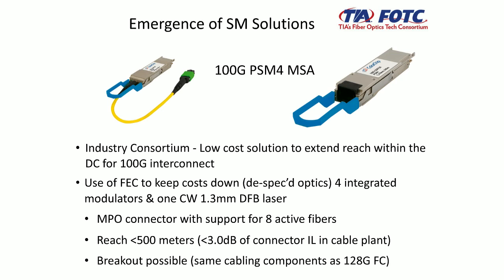This device actually has a single laser. So there's only a single source in this, but there are 4 lanes. And what they do is the laser runs at DC. It's just a lamp. And integrated in line, it's a power splitter. So I split out 4 ways, and then I have an inline modulator in each of those lanes integrated into the device. So these are very cheap, and like I say, 500 meters is,